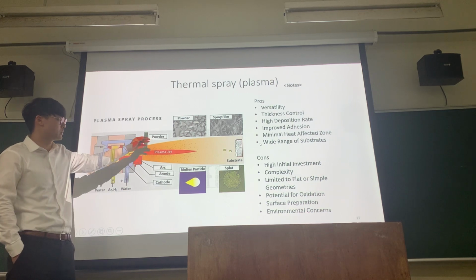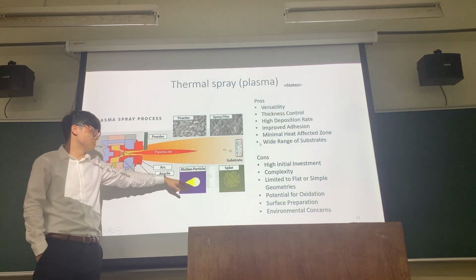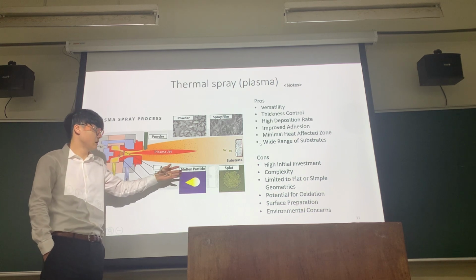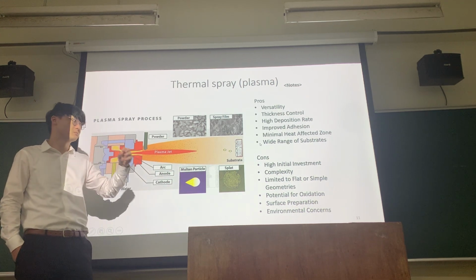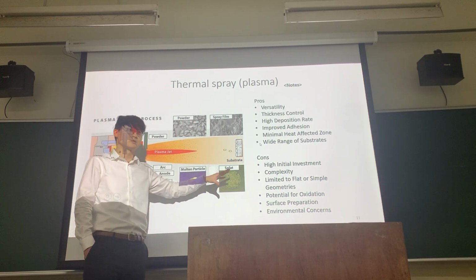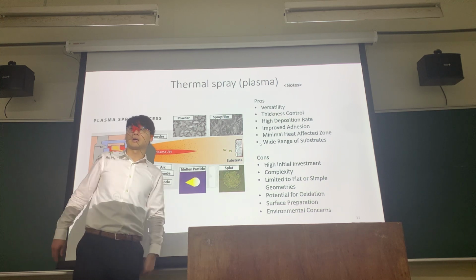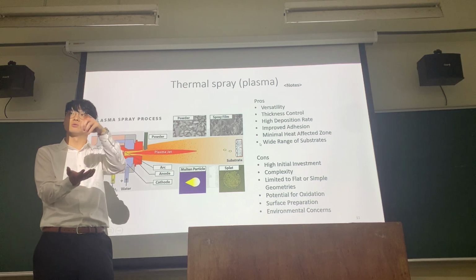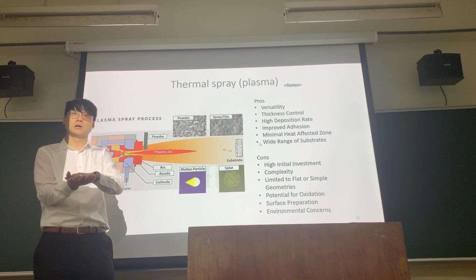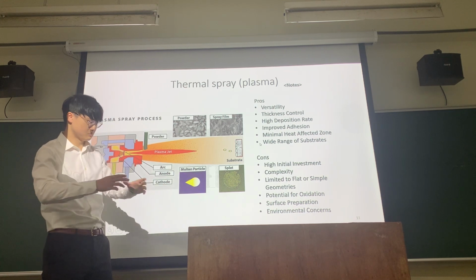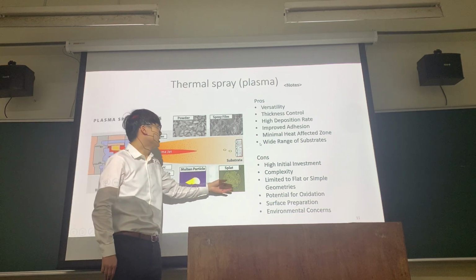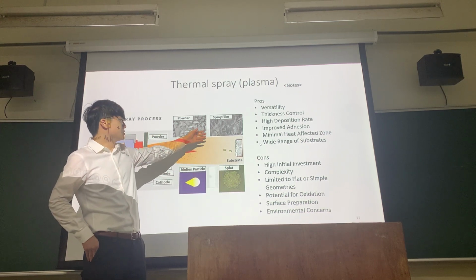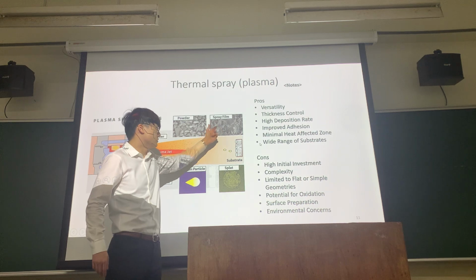When you spray, you can see you have molten particles, right? So it's being dumped down. And the typical feature you see for thermal spray is that it's flat. It's like a liquid form, like ketchup that drops and then is smashed into it. So think about liquid and the smash, right? It's splattered out like a flat thing. So a normal deposit you will see is like a spray film over here.